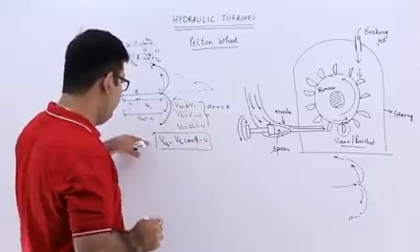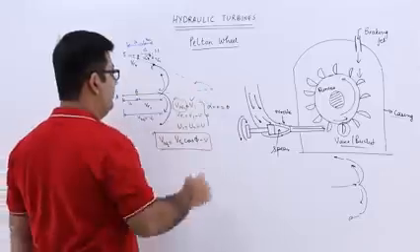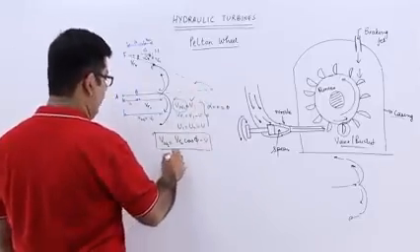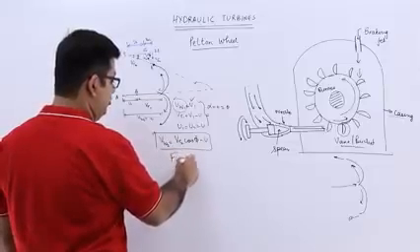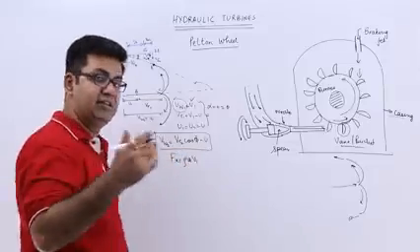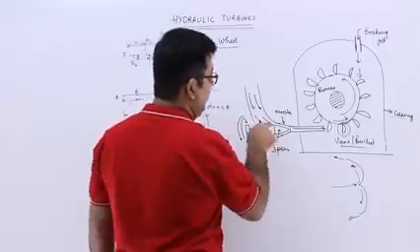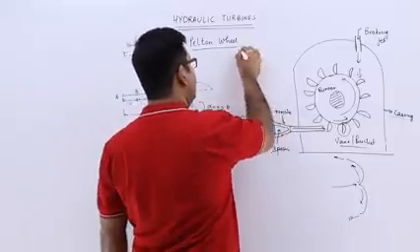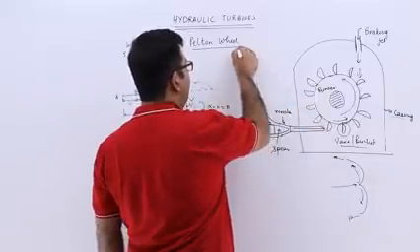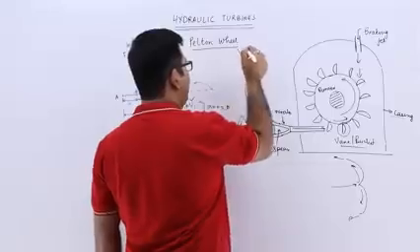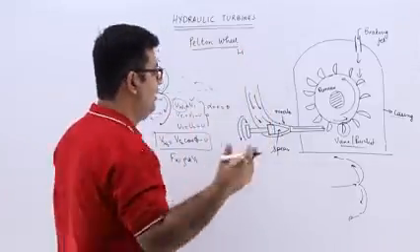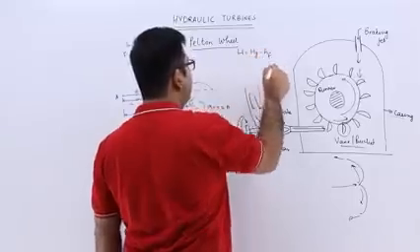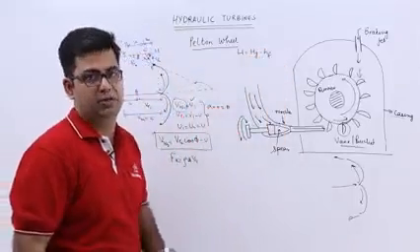Okay, so you have VW2 and you have V1. Okay, so let's use them. So your value of Fx would be equal to rho A into V1, because V1 is the velocity of the jet which is striking the entire bucket. So if you look at this, the value of V1 can be found out with the help of this formula. So let us say the net head available at the inlet is your gross head minus the head loss due to friction in the penstock.